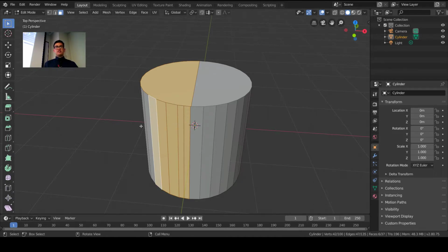But instead of having to do so many clicks, you can also use something called the circle select tool. If you press C, your cursor will change into this circle. You can press C and click and drag the circle around whatever you want to select, and you'll be able to select everything that collides with your circle.